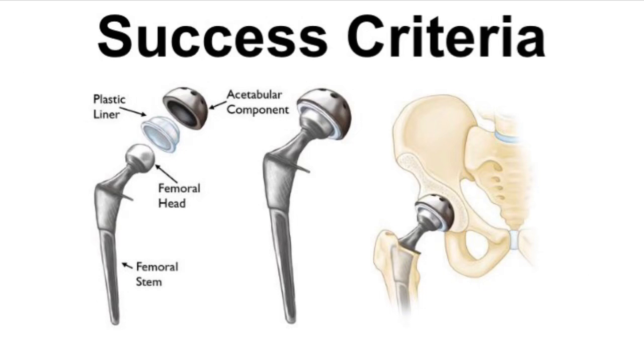The success criteria for this project is that, as we know, currently most of the commercially available stems of the hip implants are solid, without pore structure. The shortcoming of this design is that the implant is much stiffer than the surrounding bones, leading to stress shielding. A pore structured implant would potentially solve this issue. Additionally, a porous design would allow bone growth into the porous structure.